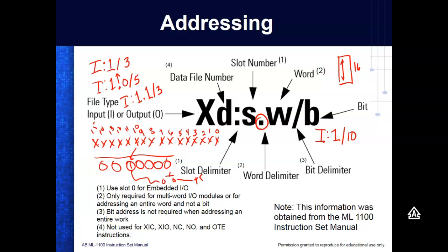So we could technically come over here and put 2 push buttons, and now we're setting up what we call a logic AND, but it still would be one address, right? You can hook up push buttons in series. You can hook up parallel. Usually we don't do it that way because I might want to use this push button later by itself. So normally every input device we give its own input port.